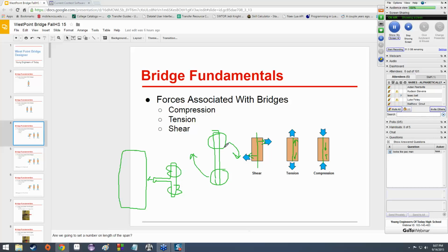Anyway, this vertical bar right here, there is shear being exhibited on that, right? Because you can think of your hands trying to turn it. At the same time, you've got the friction on the nut keeping the thing from turning. So there are a few things all working together, but in the end, that is like shear, as opposed to tension or compression. Tension would be your hands going upwards, trying to pull apart the bar, and compression would be the opposite. They'd be moving inwards, trying to compress the bar, just straight up or down.